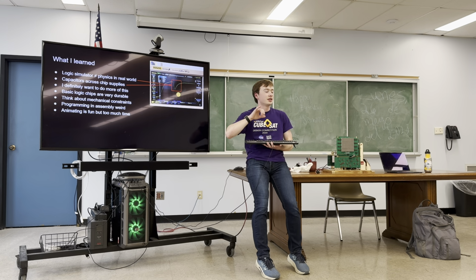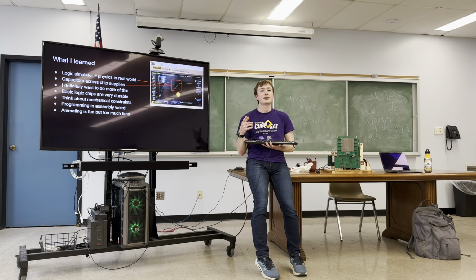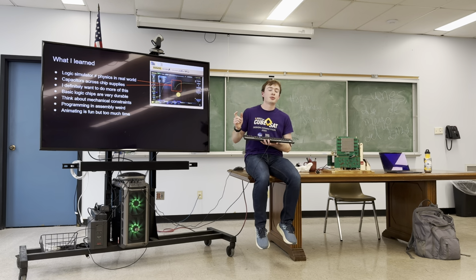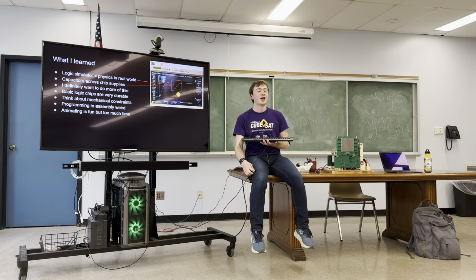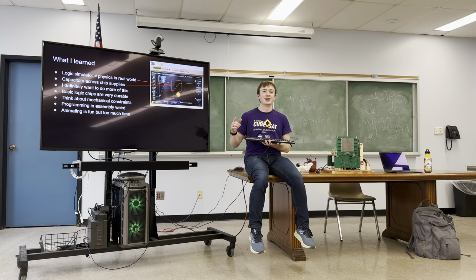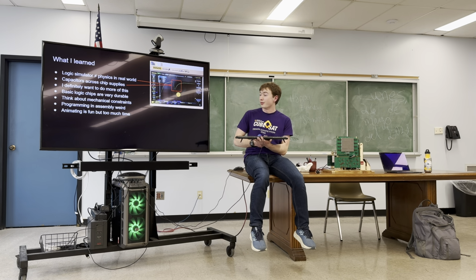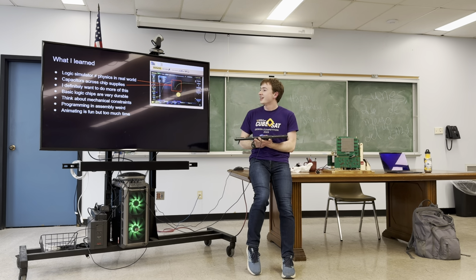When the logic chips switch states, one switch turns on and the other turns off. Dr. Hamlin, correct me if I'm wrong, but very briefly it will draw a lot of current because they're both partially on, and that causes currents in the circuit board traces that supply power to the chip, and that creates magnetic fields and complicated stuff, and that causes other signals to be messed with. So that's what's causing that to happen on the scope there.